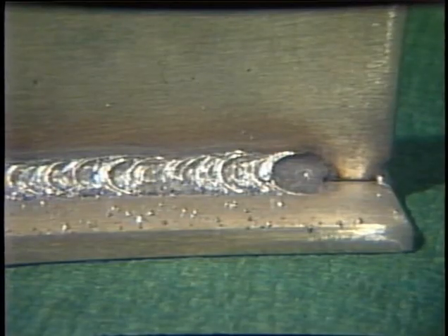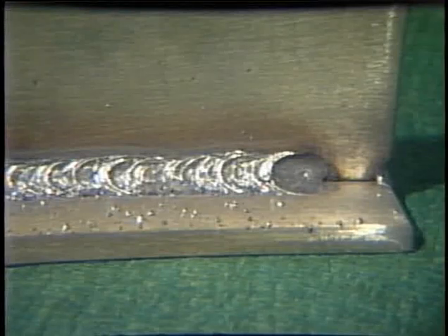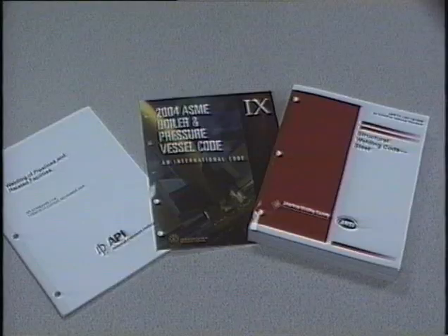Any incorrect match of mechanical or chemical properties between the weld and base metal may lead to weld failure, for example, joining stainless steel pieces with a carbon steel filler metal. In this case, the weld would not possess the same corrosion-resistant properties as the base metal. Base metal property requirements may be defined by applicable specifications or codes. Departure from these requirements may be considered cause for rejection.